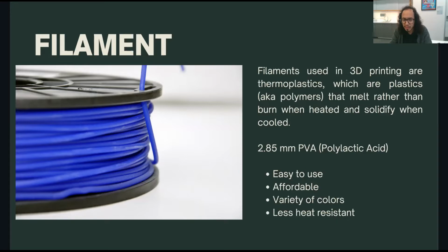And they're less heat resistant, which is kind of a con. You can't use it for any food application. So if you're wanting to make cups, you can't put them in the dishwasher. You can't leave it in a hot car. It'll start warping and oozing, and it can get a little messy. If you are interested in using this for something like Tupperware, glass, anything like that, you'll have to check with the specific vendor, because different filaments are made of different composites and have different settings and temperatures, so you'll just have to verify with them.